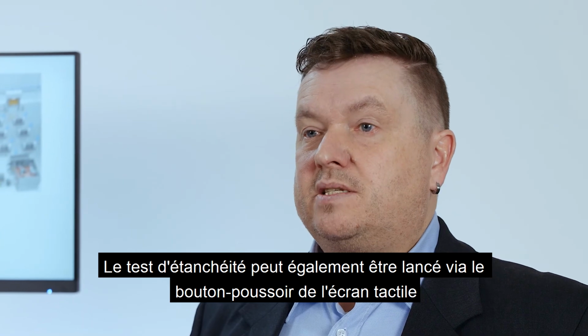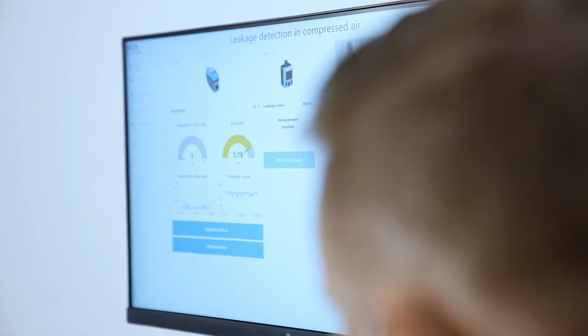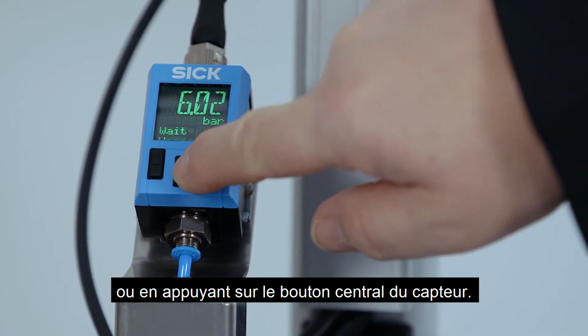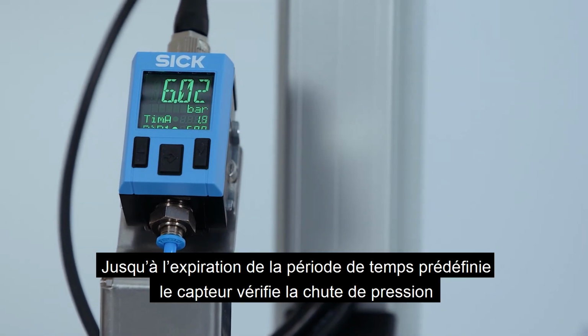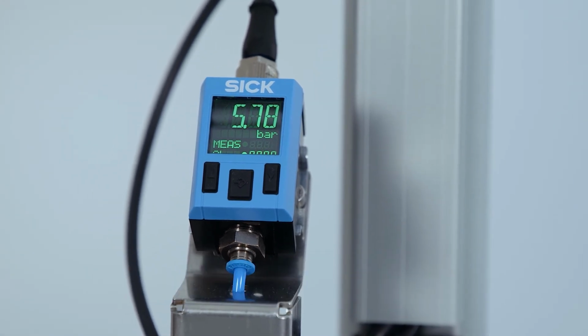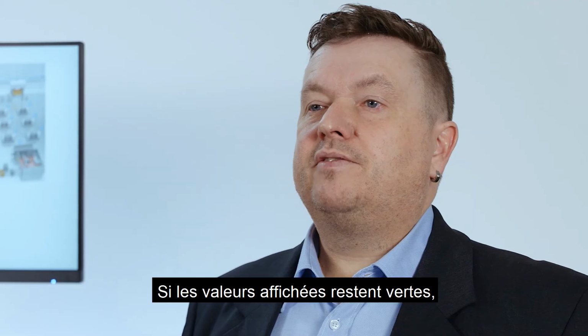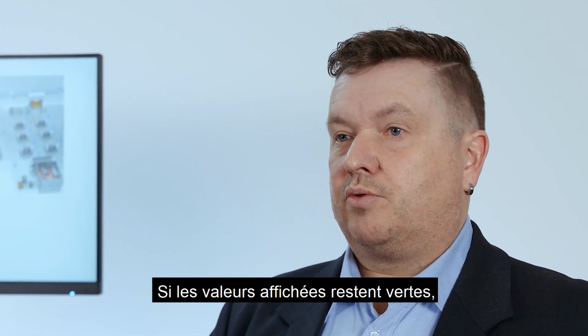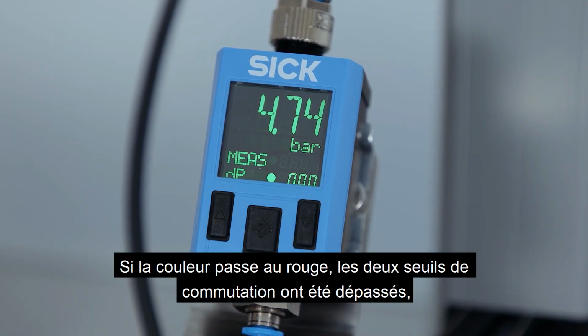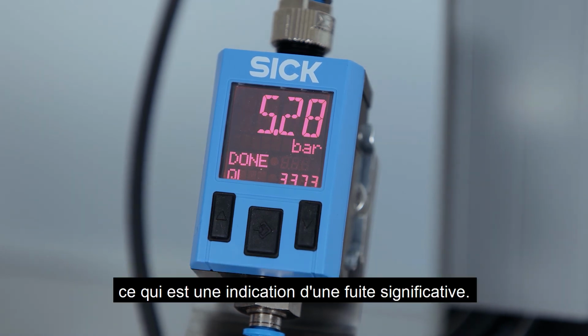However, the leakage test can also be started via the push button on the touchscreen or by pushing the center button on the sensor. The preset time expires and the sensor checks the pressure drop and if the preset pressure switching thresholds are reached. If the values in the display stay green, everything is okay. If the color changes to red, both switching thresholds have been exceeded, which is an indication of a serious leakage.